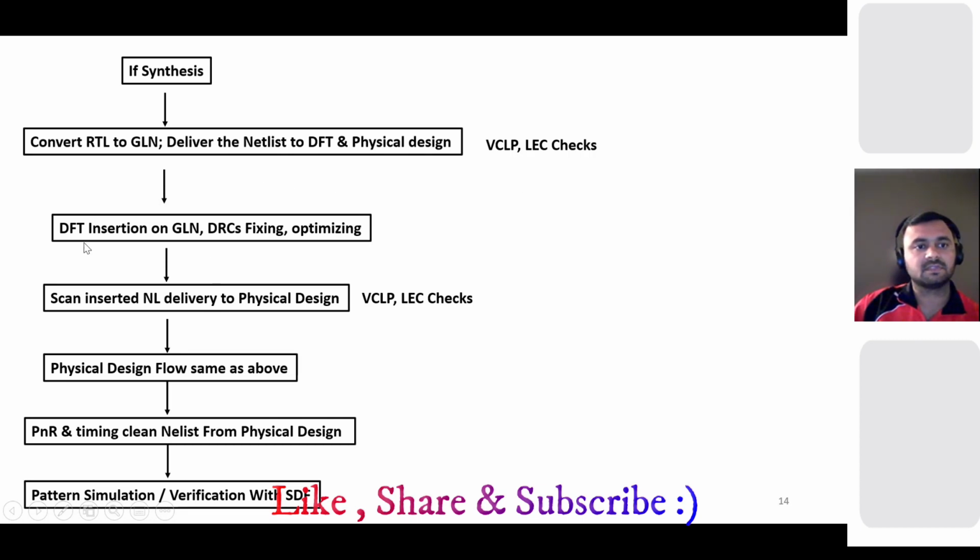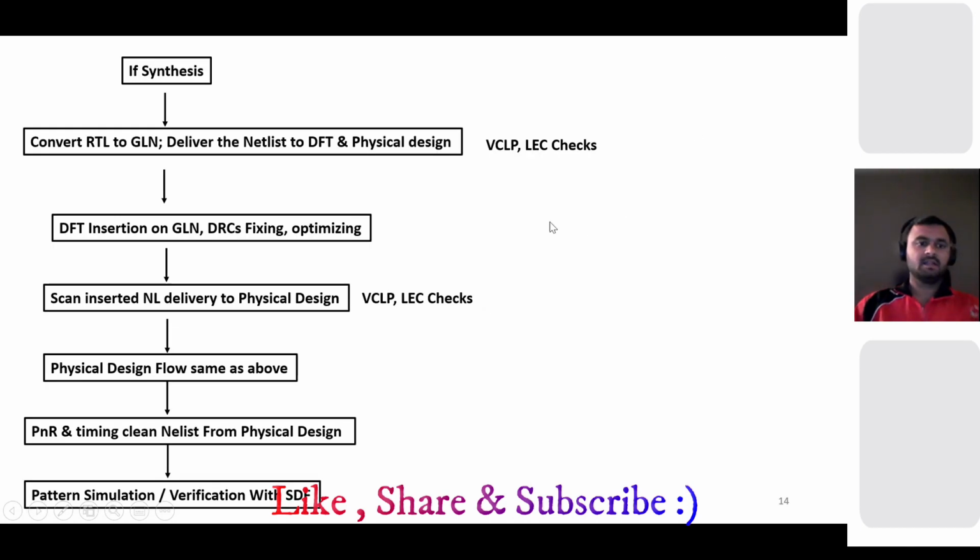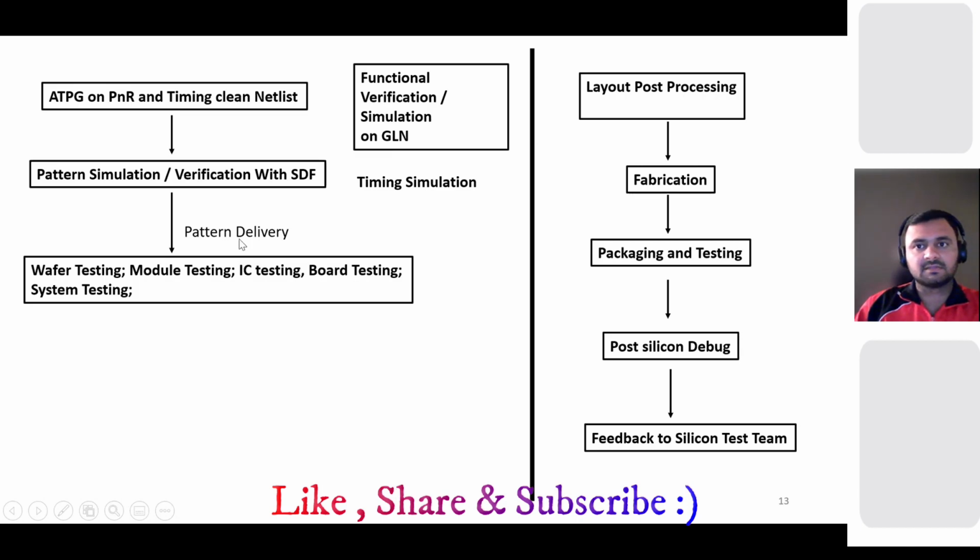And then in the next step, the DFT will do all the instrumentation and insertion at gate level. Earlier, the DFT team was doing this at the RTL level, but in the synthesis flow, they will do everything on the gate level netlist. Then they will fix the DRCs, clock DRC, reset DRC, there are many DRCs. They will optimize it and deliver the scan inserted netlist to the physical design. And the physical design flow is the same as above. So all the floor planning, partitioning, placement is the same. And then we get the PNR and timing clean netlist from the physical design, and we do the pattern simulation and verification, which we did here in the RTL case.